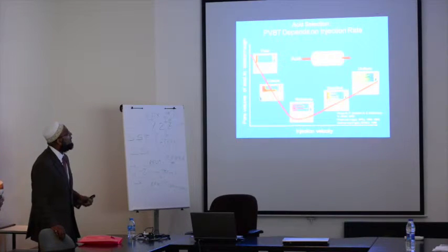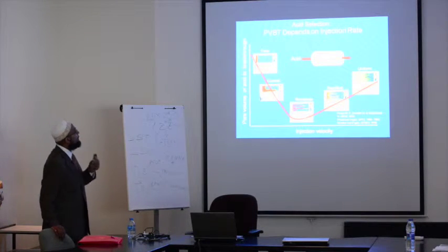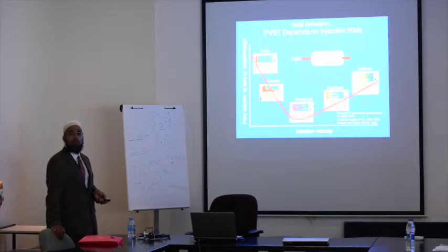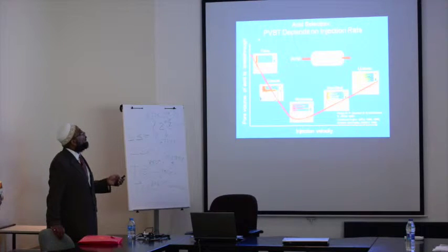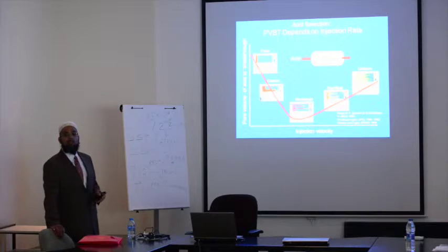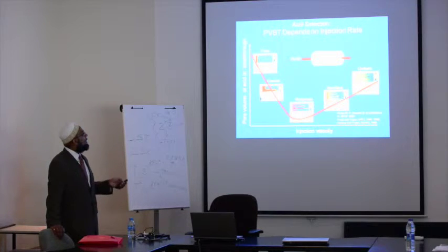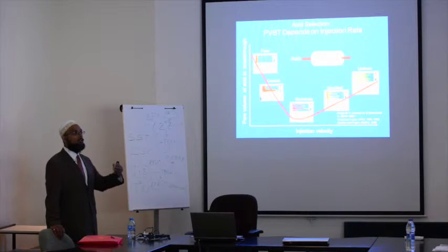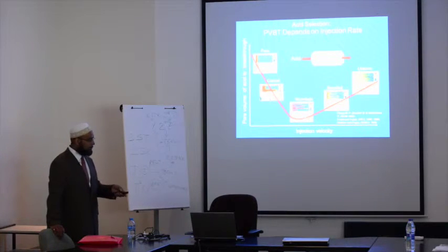Okay? I'm just going to go through maybe one or two parameters, and this one is on the injection velocity. So I have pore volume of acid to break through, right, on this axis versus injection velocity. What I have on the top colored figure is the simulation result, right? At the bottom is the X-ray of the actual core that was acidized.